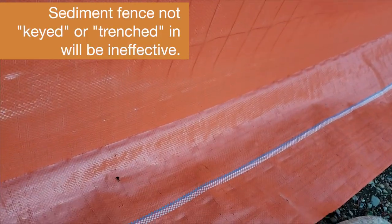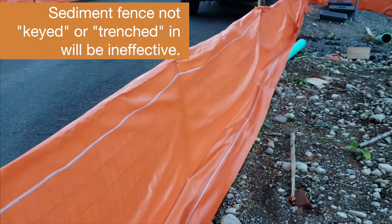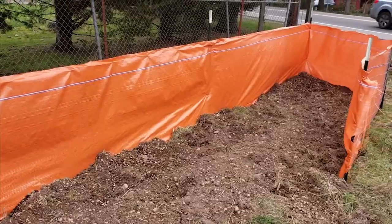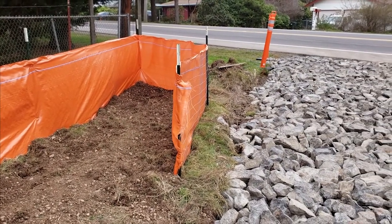When installing it along contours and along the perimeter of your project, you always want to turn the terminal end of the fence back into the project so that you're not getting water to shoot along the bottom and out into the right of way. And you want to make sure that the fence comes back into the site, creating a little pocket where the water can deposit the sediment.